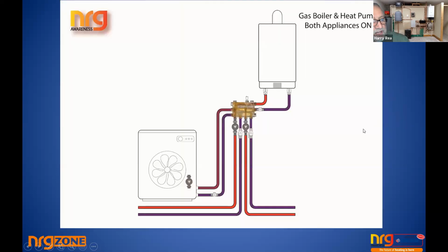But here's the trick. We have the heat pump and the gas boiler working at the exact same time. In that situation, the heat pump's only job is to catch the coldest water. Suppose we're pushing to the hilt, we have tremendous delta T, we want the most efficient job you can possibly have. Let's say we have 35-degree water coming back from, say, underfloor zones or whatever. The heat pump raises it 5 or 6 degrees, so it's gone up to 40 degrees.